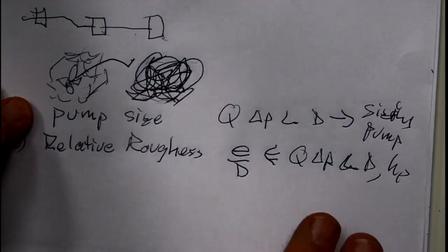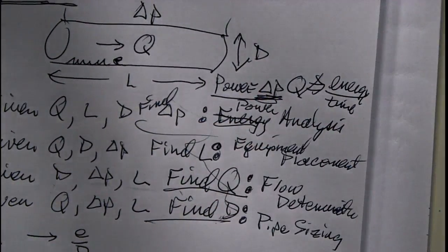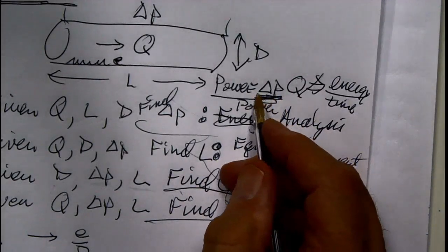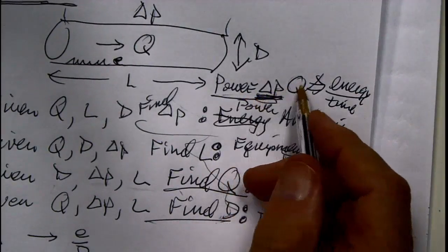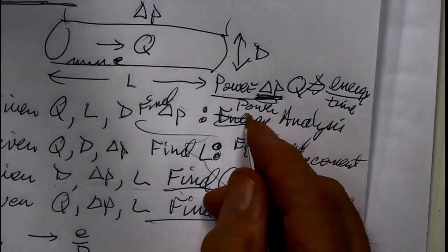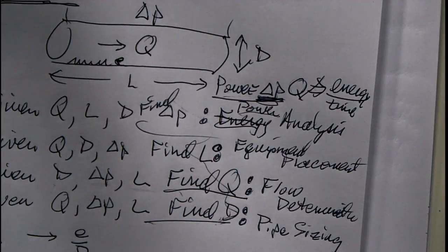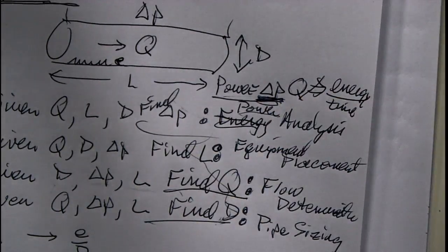Now, energy analysis up here, to run equipment, you have to sacrifice pressure drop, basically. There's a pressure drop in your body, for example, how much energy your heart is putting in. This is probably the pressure rise across your heart times the volumetric flow rate tells you how much power your heart is using. If we get away from the bio area, just having power analysis, lots of equipment requires you to give up pressure drop. Heat exchangers, for example, you have to have a certain pressure drop to accomplish the heat transfer.